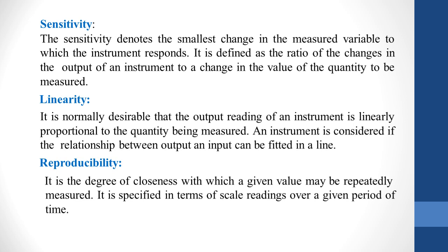However, most of the time it is necessary that the measurement system component should have linear characteristics. For example, the resistance used in a potentiometer should vary linearly with displacement of sliding contact in order that the displacement is directly proportional to the sliding contact voltage.